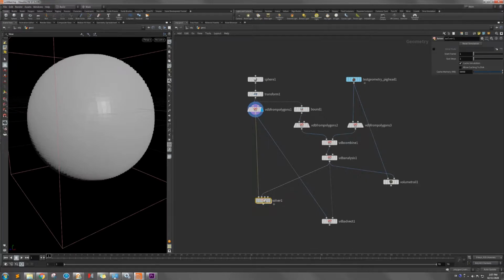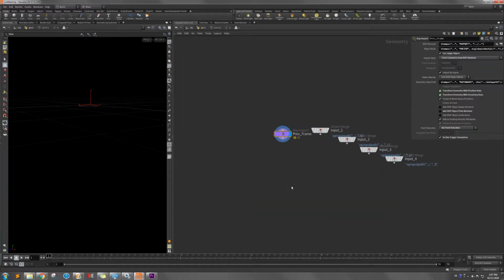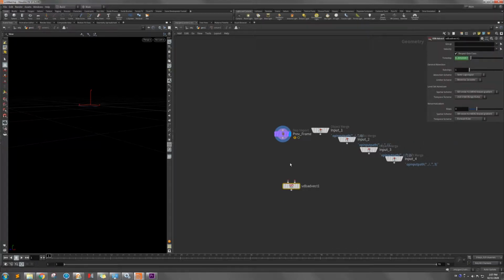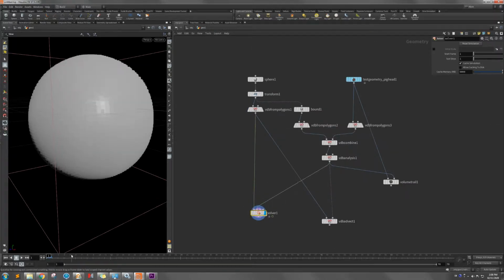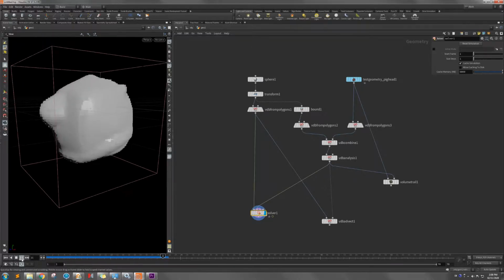And put this second frame. So actually the solver will do the iteration for each frame and use the previous frame in the current frame calculation. So in the solver, we need to add the VDB Advect here actually, and use the previous frame as a result, and use the second input for the speed, the vector, actually velocity. So check here, so that we will use this node as result. Check it out. Let's play it again. Yeah, that works.